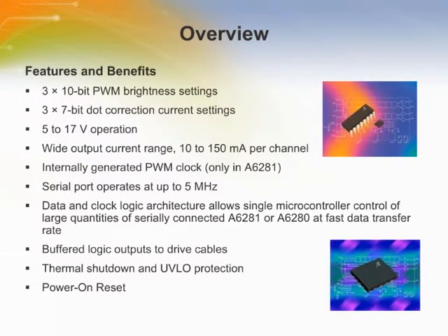The A6280 and A6281 LED drivers from Allegro Microsystems are 3-channel constant current LED driver ICs with programmable PWM brightness control. These devices are ideally suited to driving clusters of red, green, and blue LEDs in applications where a cluster forms a single pixel, as in large displays or lighting fixtures.